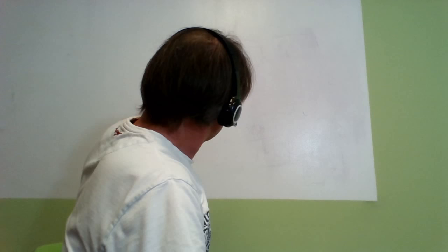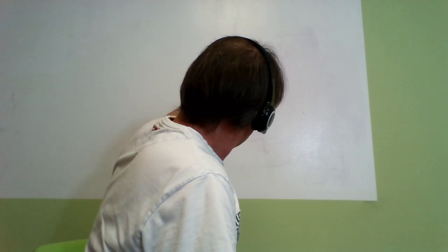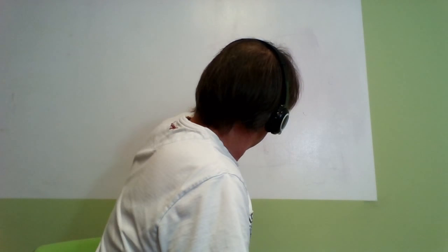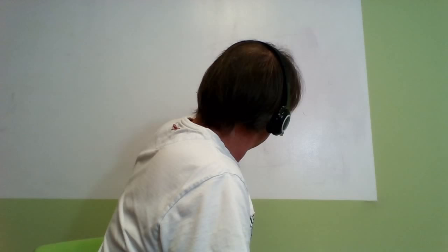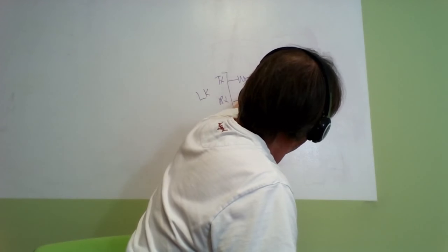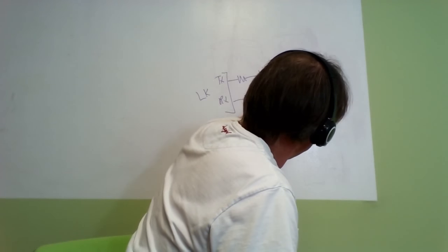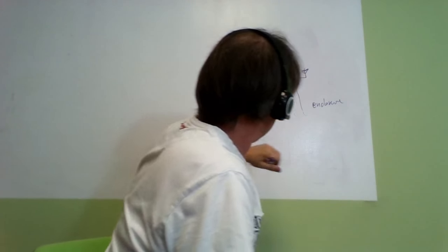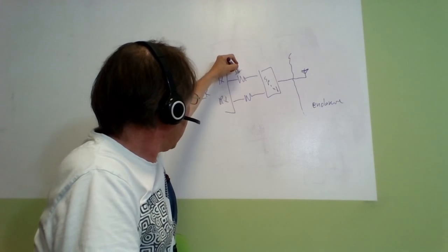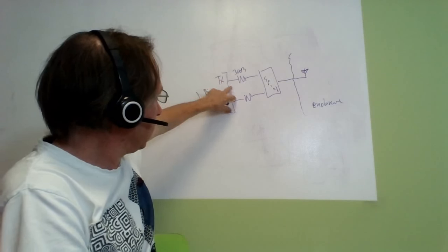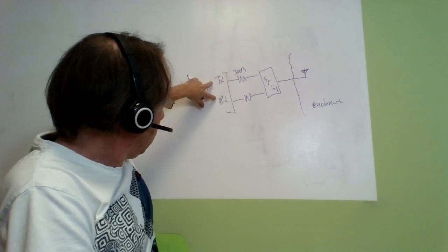So we have the transmit and receive ports on the LabKit. And we have a splitter combiner. And in the case that Rob's talking about, this goes to an antenna port inside an enclosure. It's important that you have attenuation here on the receive and transmit before they get to the splitter.